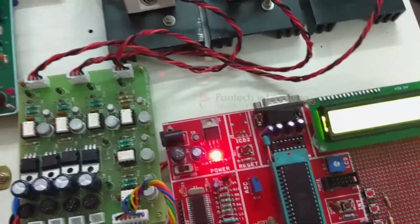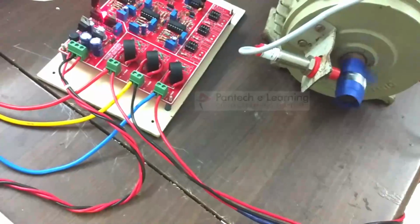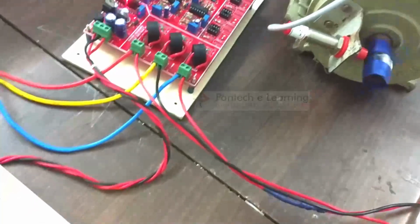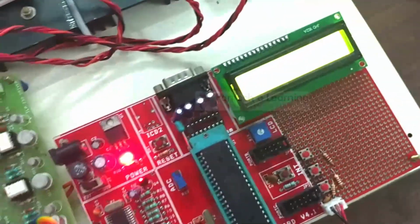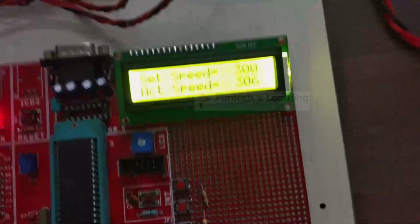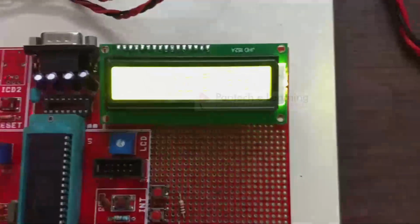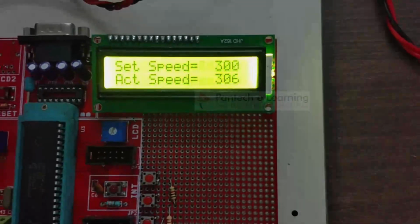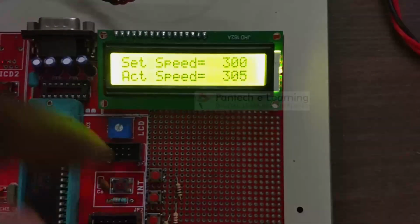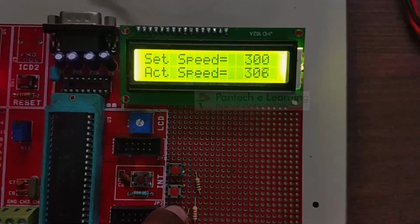Now increase the input AC voltage by using the auto transformer. The motor starts to rotate at the set RPM. That is, this part is a closed loop. So whenever we set the set RPM, based on that the actual speed will be maintained constant at the set RPM. Now I am going to increase the set RPM, set speed.